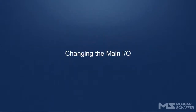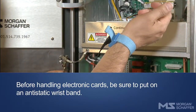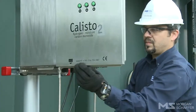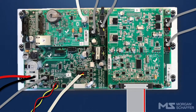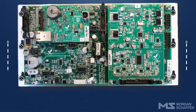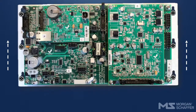Changing the main I/O. Before handling electronic cards, be sure to put on an anti-static wristband. Turn off the Calisto and close its circuit breaker. Open the Calisto's door. Unplug all of the cables that are connected to the main I/O. Loosen the 6 screws that are holding the main I/O without removing them completely. Remove the main I/O with its support plate by carefully lifting the assembly before pulling on it.